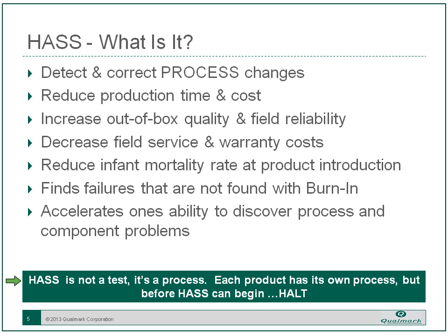It can make perfectly good sense if you have a burn-in plan to reproduce it for all your products. But with HASS, it's dedicated to each product because the limits that you use in HASS are based on what you learned in HALT. And we've been through that several times, I'm sure, so if there are any questions on it, you can refer back to some of our past webinars for details on how we get to that level.